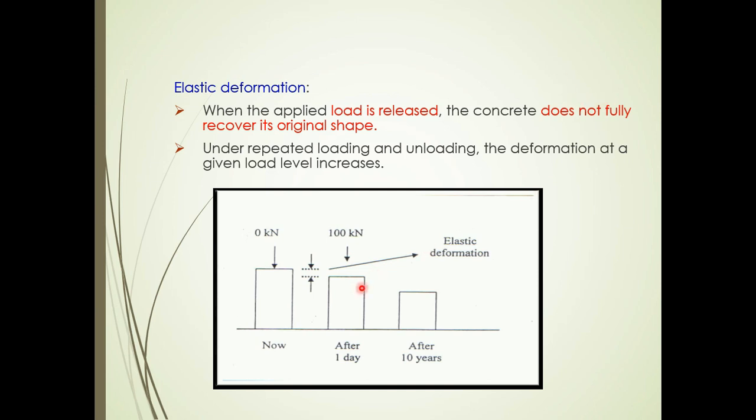Okay, so here for example, for the initial state, we do not put any loading. Okay, and then we put 100 kilonewton. After a day, we see some deformation. This is what we call elastic deformation. And if we leave the loading for 10 years, for example, for a longer time, then the deformation will be more.